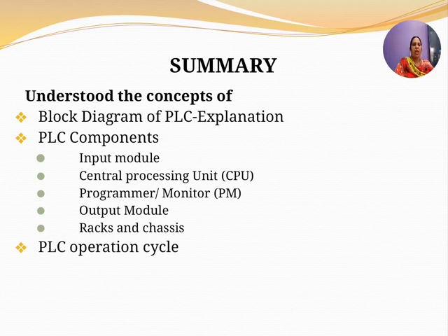Then lastly we have the communication interface module. This module is used to transfer information between the CPU and the communication networks. Intelligent I/O modules are used. These communication modules help to connect with other PLCs and computers which are placed at a remote location. So this is about your communication module.